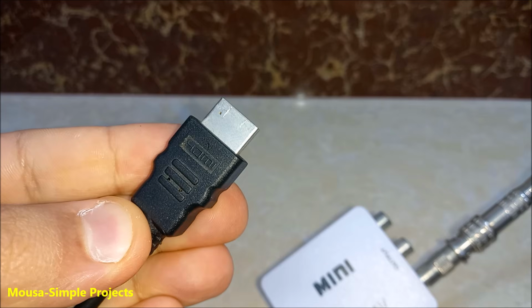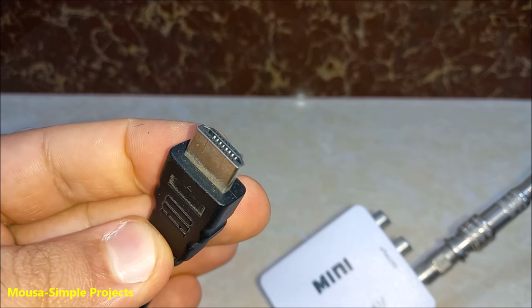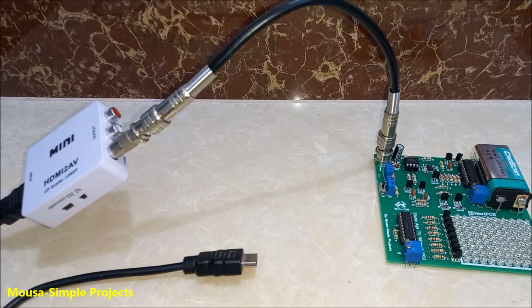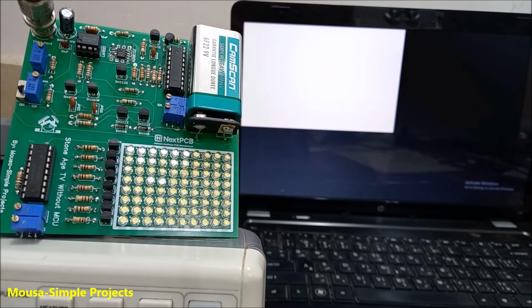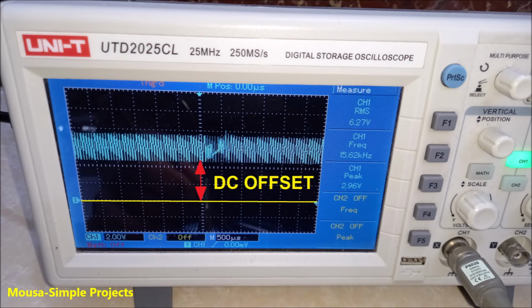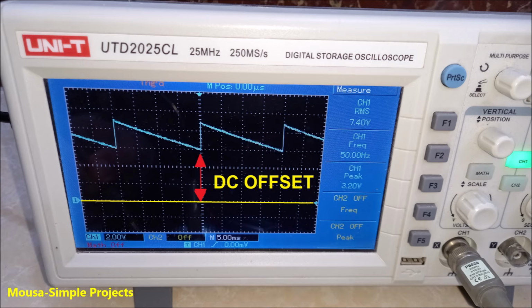I want to use the HDMI port of my laptop as a video source, so I need this adapter to convert the HDMI to composite video. For the first time using this circuit, the image will be out of the frame. That's because the signal of the x-axis and y-axis has DC offset.